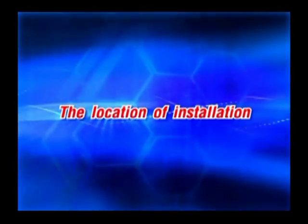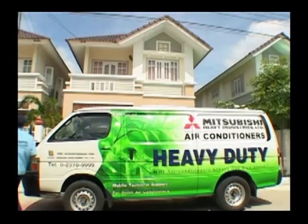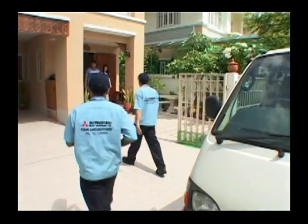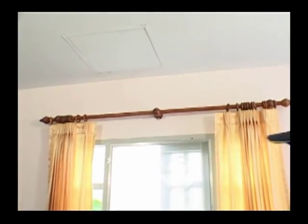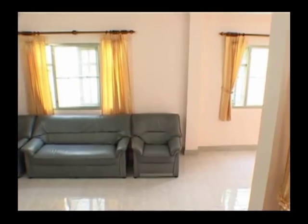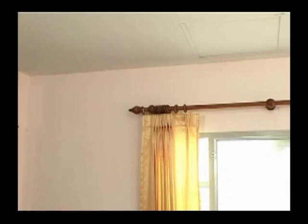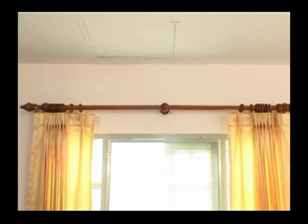For the location of indoor installation, there are points for consideration as follows. An air conditioner must be installed where nothing will block its airflow and its cool air can flow all over the place. It must be installed on a firm and strong place to prevent the vibration of a wall or the air conditioner itself. There must be enough room for repair and maintenance.